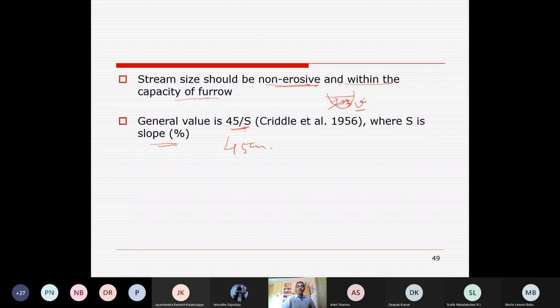And this is a general guideline to minimize land grading operations: the method used should be adapted to natural topography. The slope of the furrow should not cause any erosion problem. That's why there is a maximum allowable slope for different soils.